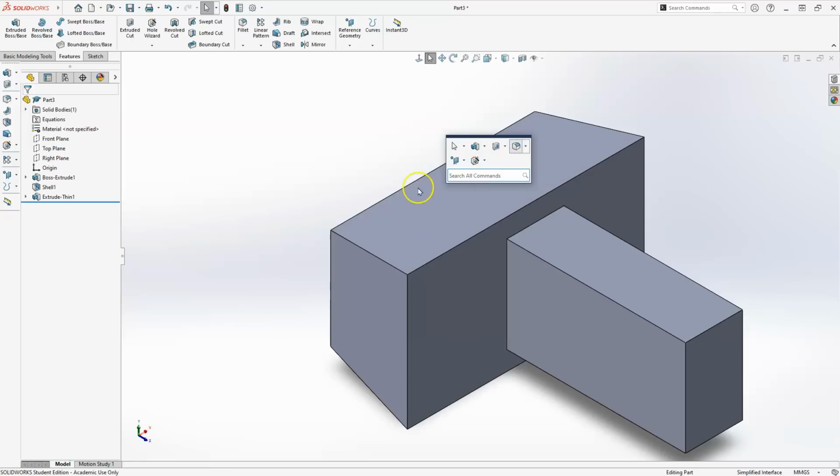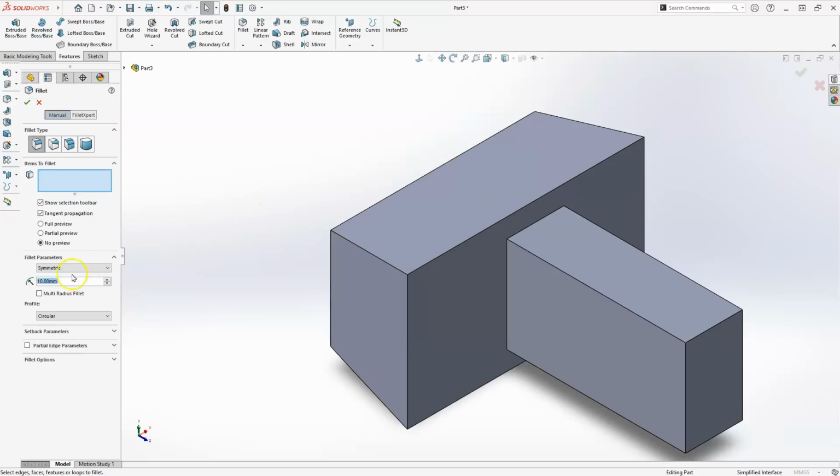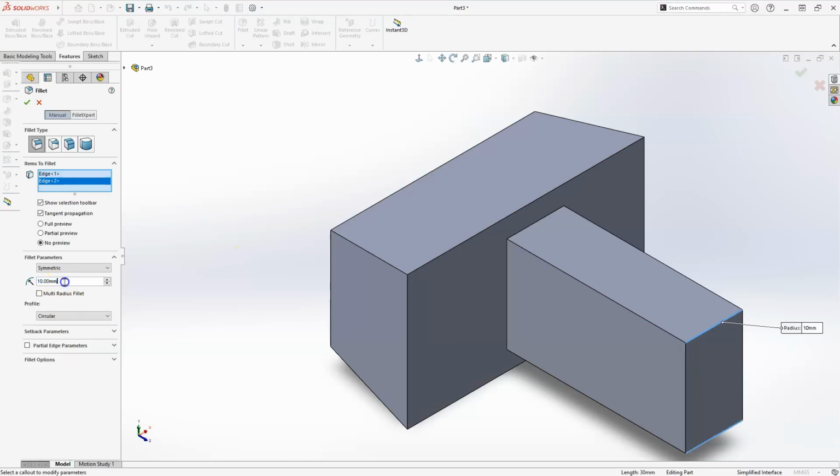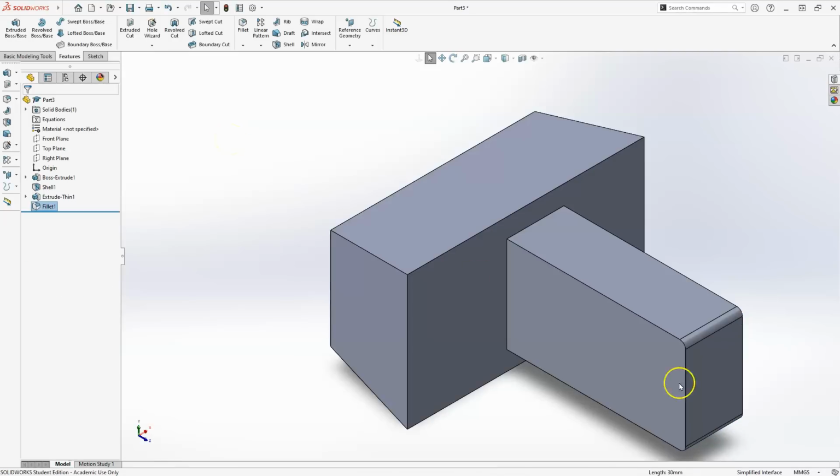So if I want to go to fillet, I'll wait for it to pop up over here and give me a radius and things of that nature, and then I can just go ahead and place them on here. So I can go ahead and pop a radius on these two, and it might be too big, but let's go ahead and make that number somewhere around 3. All right, and that should be enough. All right, so then it can pop those radii on, but that's just using the S button, right? So anyway, that's probably about enough as we need to see about SolidWorks.